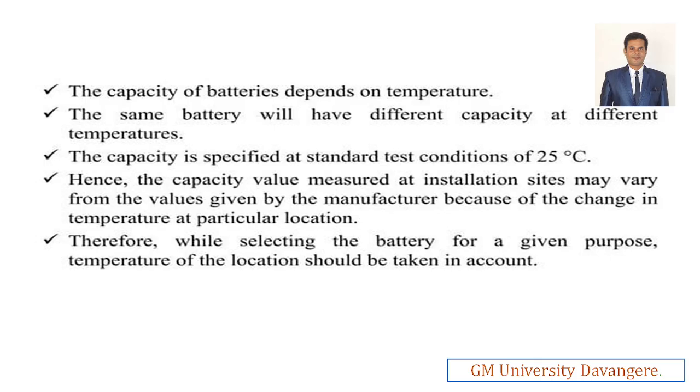It is a very important factor to take care of for the life cycle of the batteries. We have to see whether it will give life for more years or for fewer years. Everything depends upon the temperature. If the temperature keeps on rising, the degradation will also rise very soon. So with respect to these factors, we have to see the battery condition and the battery life, which is based on the temperature of the batteries.